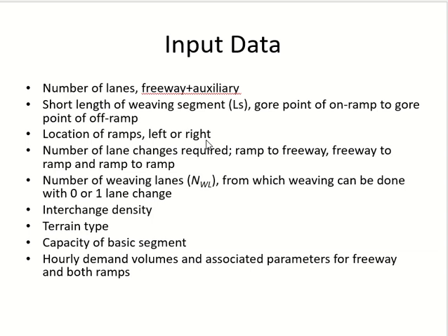We have used it. How do we calculate the flow rate? Peak hour what? Peak hour factor. To convert to flow rate, we need the peak hour factor, right? And one more thing, the percentage of heavy vehicles, to convert to passenger cars. So these mean the percentage of heavy vehicles and the peak hour factor. Okay, clear?